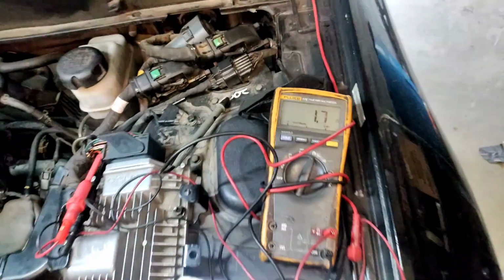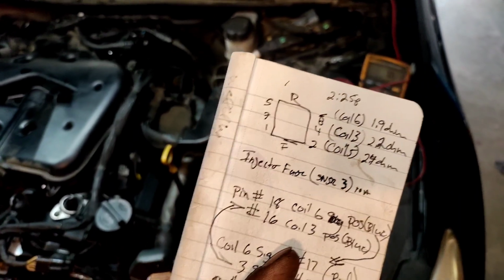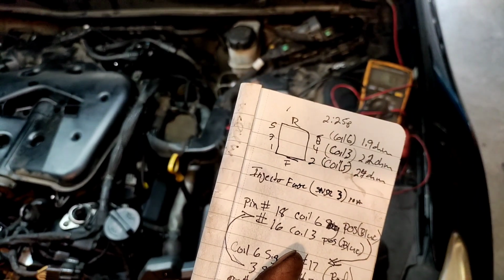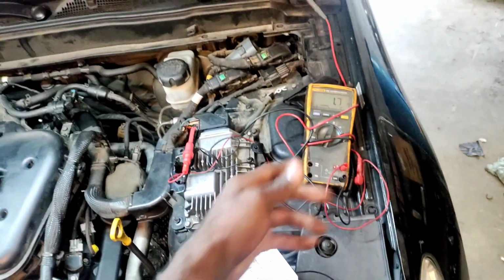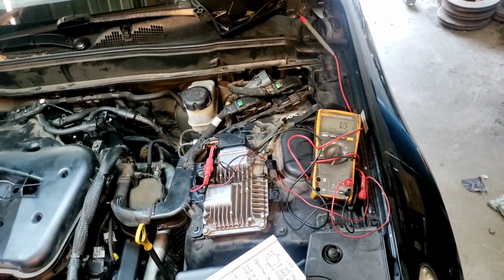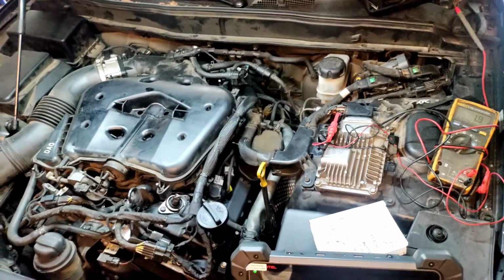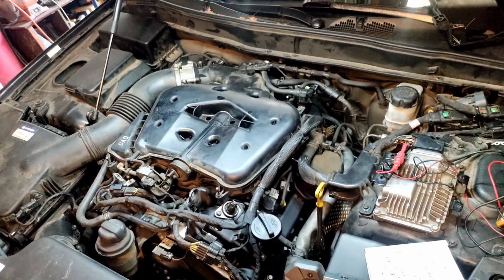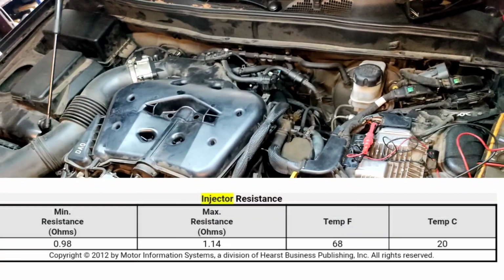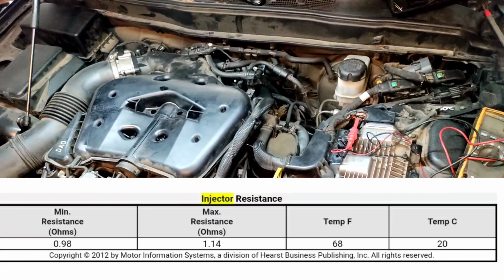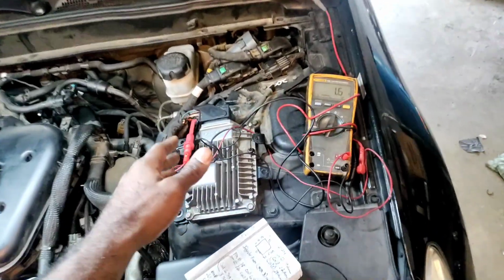It's fluctuating between 1.6 and 1.7 at about 100 degrees. Before it was 2.2 ohms at about 190. Right now it's 1.5, 1.6 ohms. Recommended ohms for the coil is supposed to be around 1.2. But again, I checked the others that aren't generating a code or posing a problem, and they were all around the same. I did the same test I'm doing now.